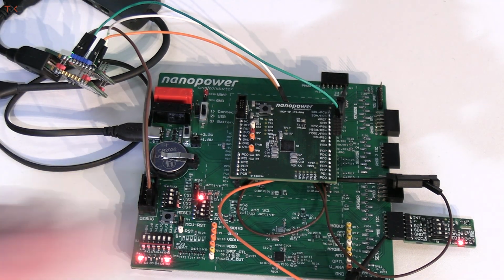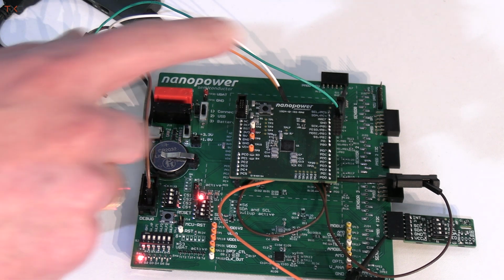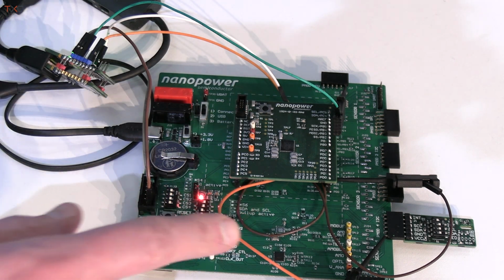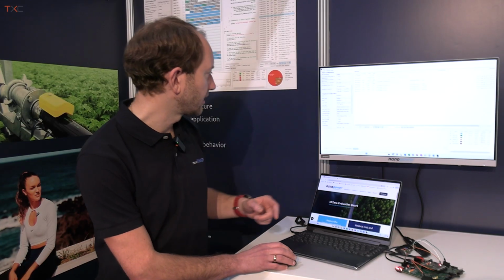In this case, we're just using one temperature sensor over I2C, but you can connect up to 2 I2C sensors and 2 SPI sensors to the evaluation board. And then on the left, you can see this small sniffer module, which I made based on the Nordic dongle. This one is connected to the I2C, to the UART, and to some of the enable pins for the sensors and the host. And that's why it can toggle the pins, or everything that happens on the board can be reflected in the interface over here. And let's see if it's actually connected.